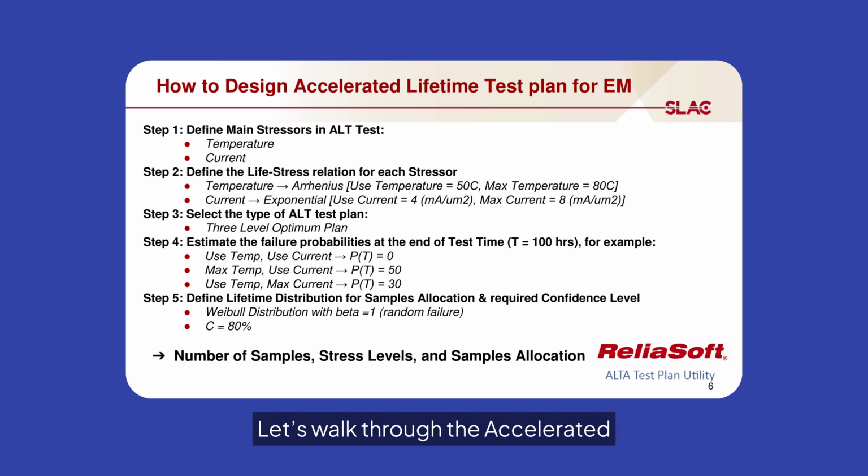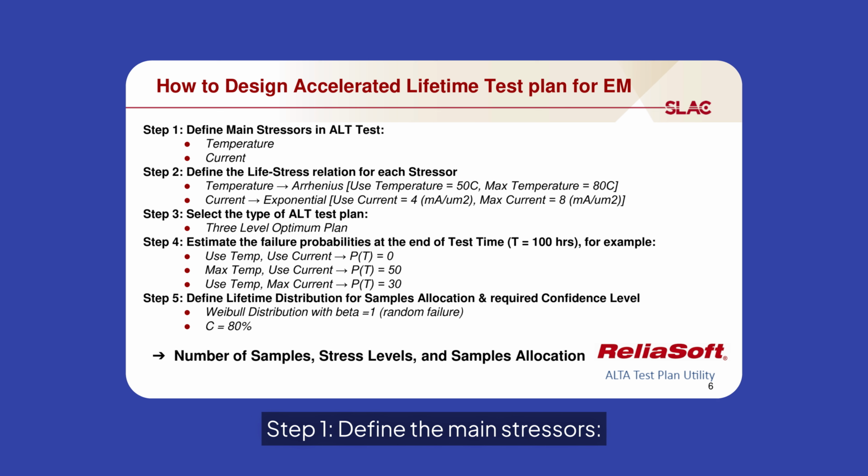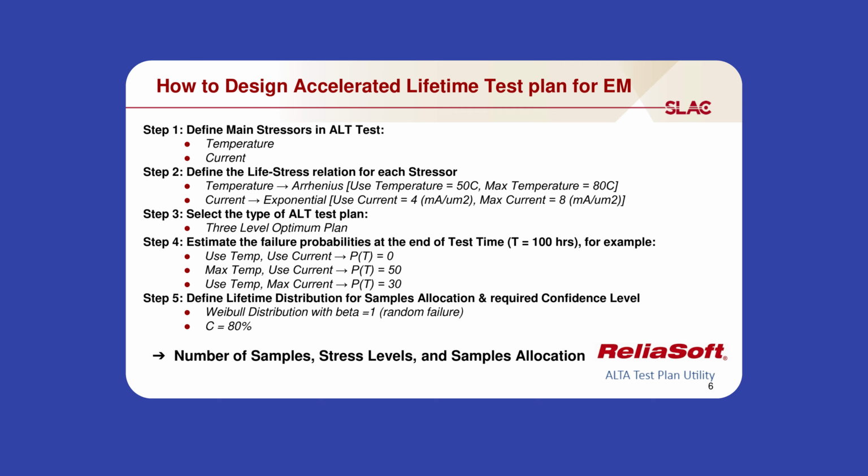Let's walk through the accelerated lifetime testing plan step by step. Step 1. Define the main stressors. First, we identify the key stressors that will drive failures during the test. In our example, these are temperature and current.